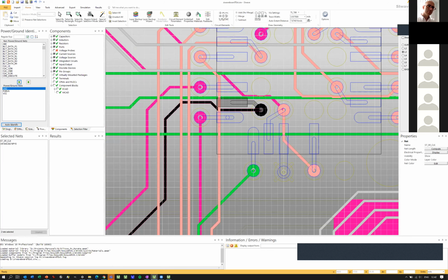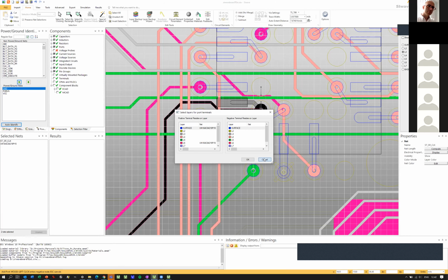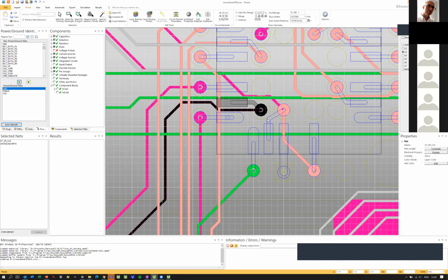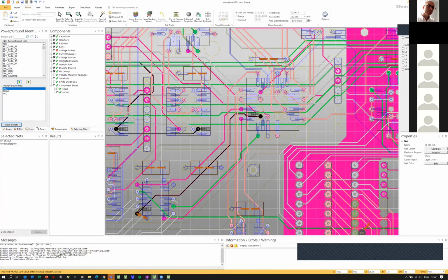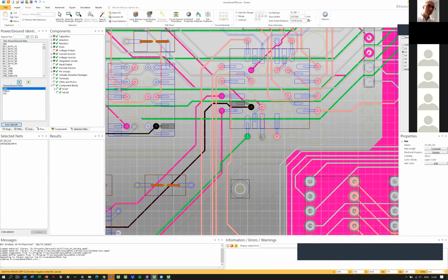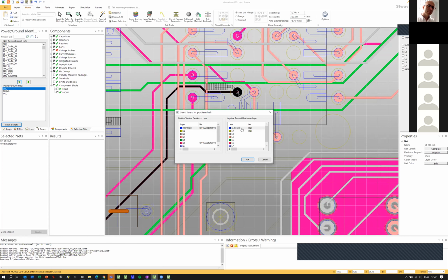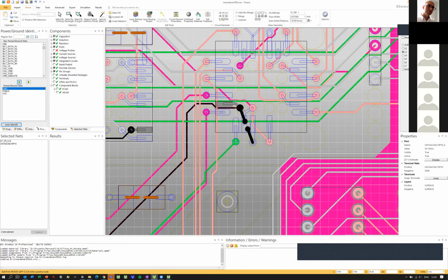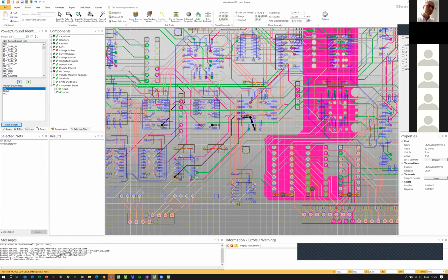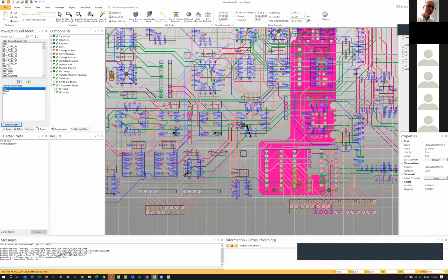Okay, once again. Where's my ground? Maybe here? No. I should find a ground reference somewhere. Once again. Where is my ground? Maybe here. Okay, that's ground. So the length is not important. This is kind of ideal excitation to this single small net in here.